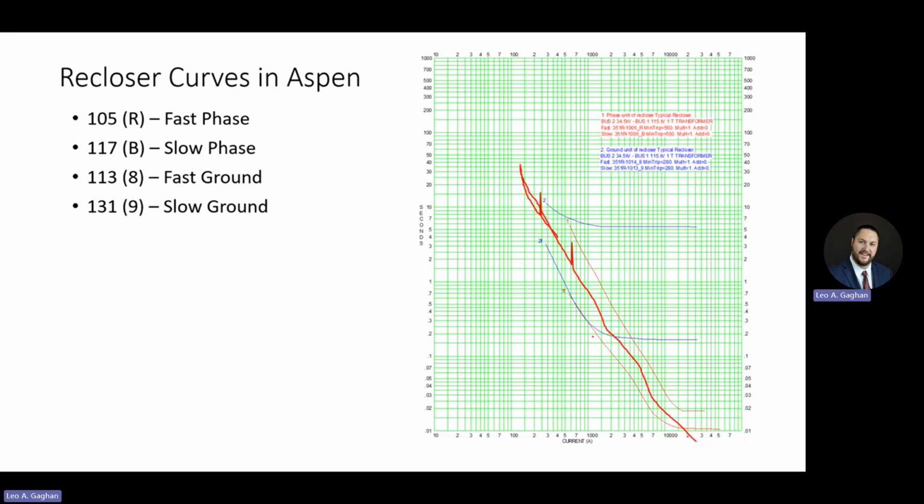That's great. No one lost power for an extended period of time. It costs a lot of money for the utilities to send out these technicians to first find the blown fuse, and then replace it. So there's a reduction in operating costs. Like I said, the only real downside is the whole circuit lost power for maybe 5 seconds, or whatever that first opening interval is.